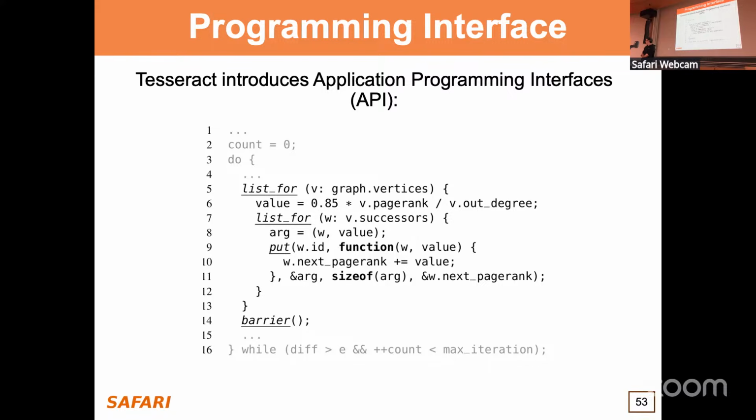I think maybe if I can add to your point, there is yet another work from SAFARI that characterizes RowHammer in HBMs. They see that the impact of temperature on RowHammer exists. So maybe when you compute in the lower dies with out-of-order cores, you increase temperature, and that can cause an increased possibility of running into RowHammer.